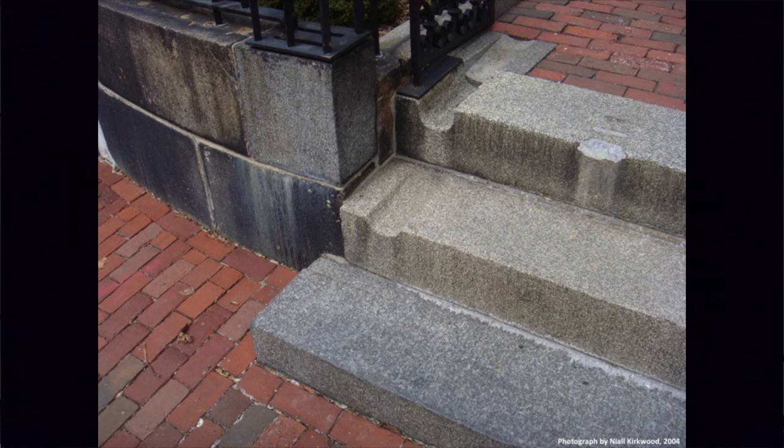Here's a more Puritan way of looking at the same thing. In New England, this is a Yankee detail, if there ever was one. This is Beacon Hill in Boston, an early 19th century stone step. Some of you have seen this. Getting things down in a matter-of-fact way, no more, no less. Three grooves cut into stone, each getting progressively shallower as you go down, which is curious because you'd expect the exact opposite, that it would get progressively deeper to catch the increasing volume of water. However, this is for the slow drip, drip, drip of November and March. This is for a very slow weathering, wearing climate.